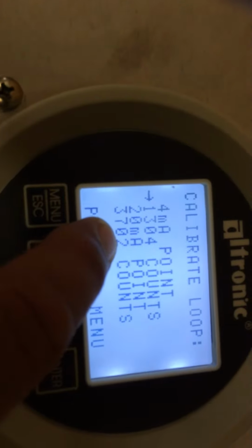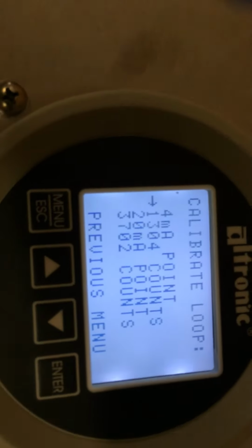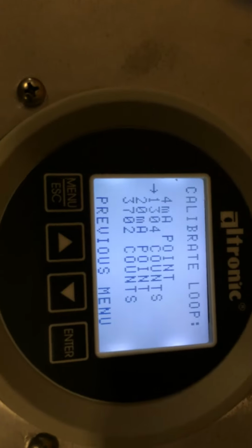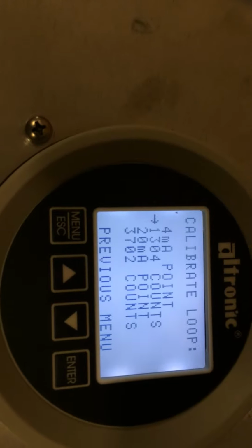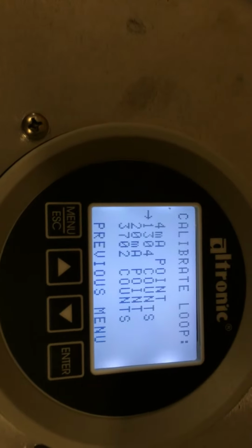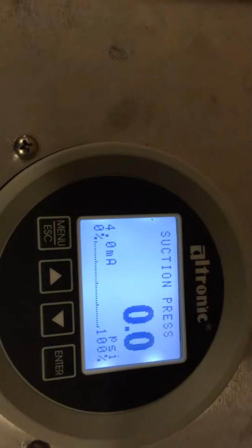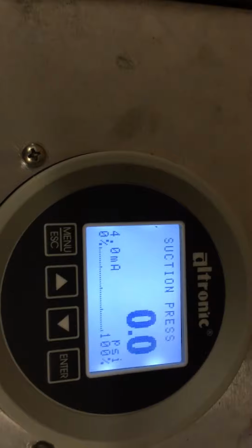These values aren't an industry standard. It's a way for us to take that 20 milliamps and cripple it a little bit, or set limits on it. So an example is, if you've got a 3516 ULB ADEM 3 system set up with the ET software for maximum idle speed at 1400 RPM, that means when you put 20 milliamps to it, it's going to run 1400 RPM. Likewise, if you set your minimum idle speed to be 800 RPM, when we put out 4 milliamps, it's going to run 800 RPM.